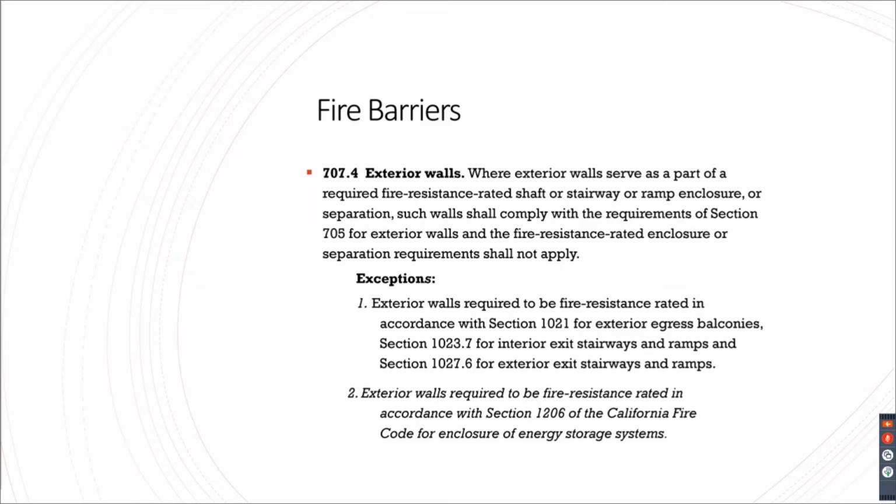So the charging section is saying, all right, it doesn't have to be rated at the exterior wall unless it's otherwise required to be rated. So if you've got these conditions that are in the exceptions, make sure that you go to those sections, to make sure that if your exterior wall needs to be rated, it'll tell you in those sections how. So yes, the charging section says you don't need to rate it, but you do have to rate it if it's otherwise required to be rated, and go to those sections that are listed in here.